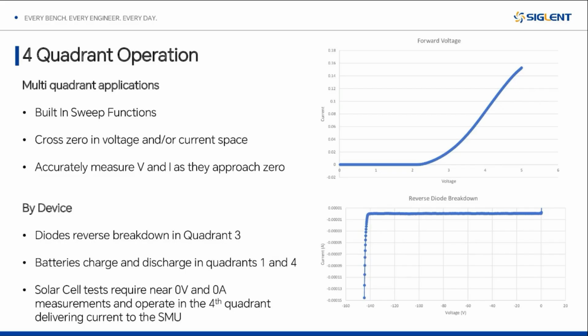So here's a couple looks at a diode, both looking at the operating range down through the reverse breakdown. Right. So again, you've got much different current levels here, many octaves, many decades of current from milliamps down to nanoamps as you approach zero and get into a reverse breakdown. So you have to be careful how you set up and analyze this data, but your ability to get that whole cycle of data in one sweep with powerful measurement capabilities on the right ranges at every step is important.